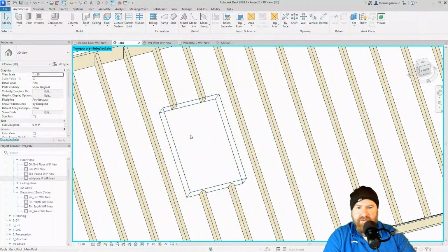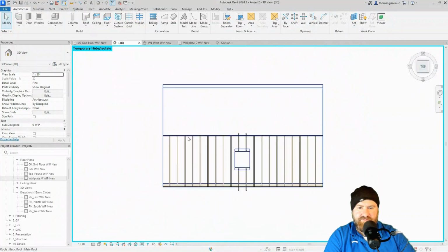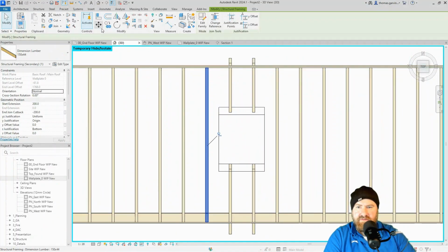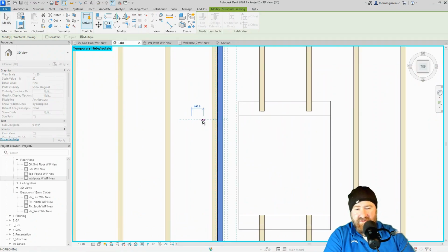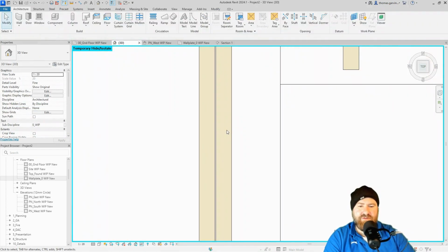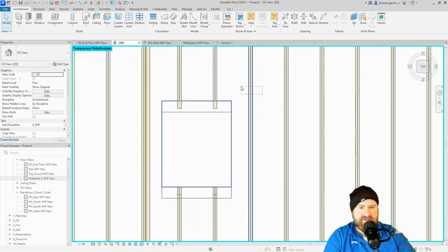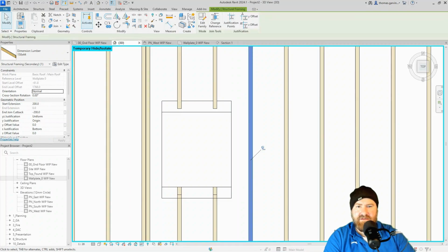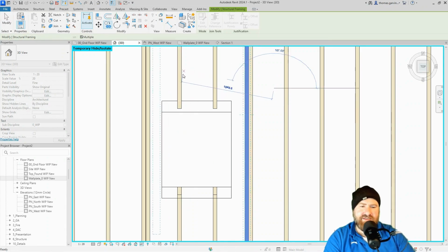So we're going to want to double on each side of the opening. I'm not going to be precise about this, okay? I'm just going to double this one up, okay? So if I go to top and move that, copy that guy across 46. It's 44 mil thick, but I just left a 2 mil gap just so that you can clearly see them in the 3D render views. And select that guy and copy across 46. So do it again. Push it out 2 mil.